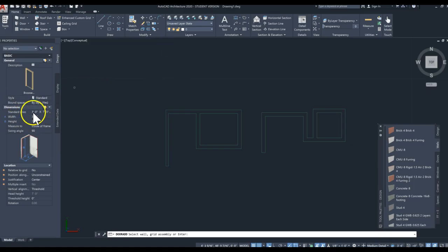And what else can we say? Well, if you want to plug in the correct width at the onset, go ahead and type out how big the door was. 3 feet, 2 feet, 8 inches, there we go. How tall is the door if you measured that? Okay, well anyway, we've got it all set, we're ready to go. And so now we click on the wall which we'd like to add the door to.